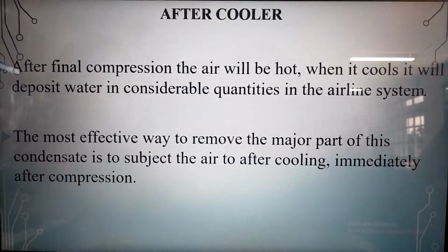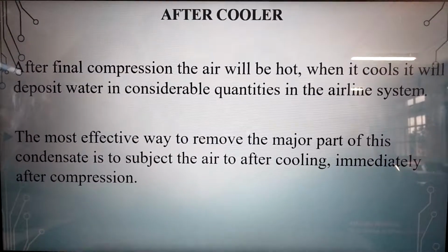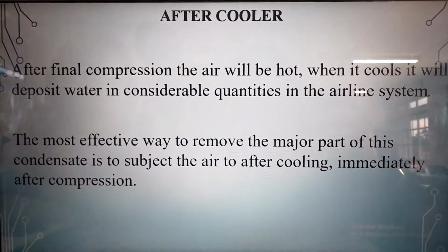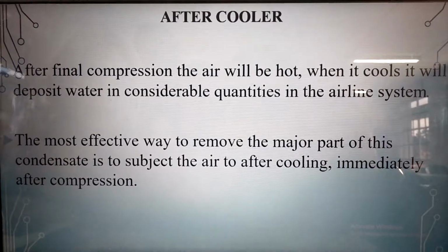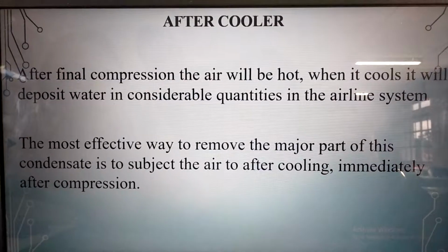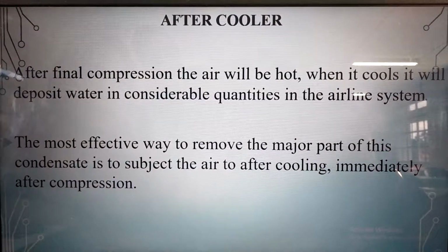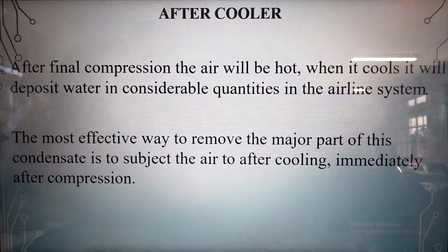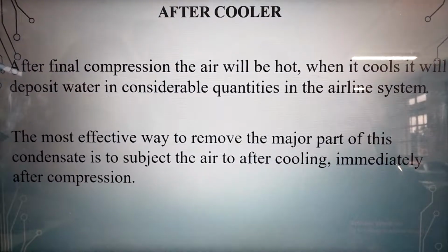Aftercooler. After final compression, the air will be hot. When it cools, it will deposit water in considerable quantities in the airline system. The most effective way to remove the major part of this condensate is to subject the air to aftercooling immediately after compression.